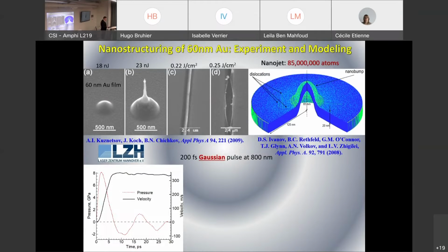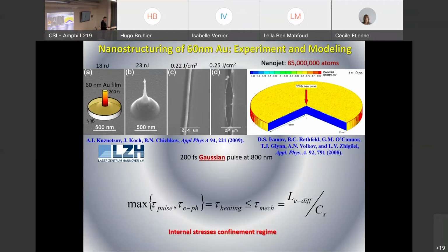This is the velocity of lift of the material in the vertical direction as a function of time. This is pressure evolution as a function of time in the central part of the material. What we can notice is that acceleration of the molten part of the material in the vertical direction takes place completely due to propagation of the first, strongest pressure wave.